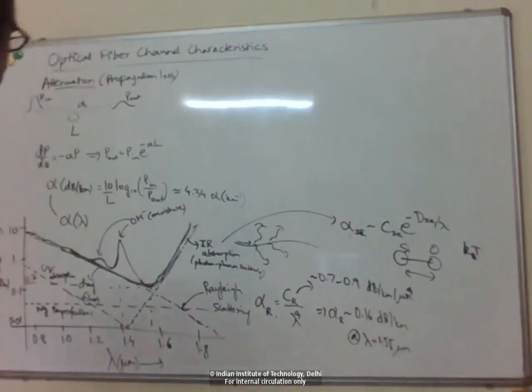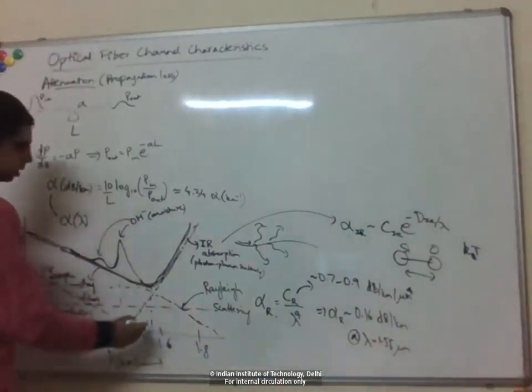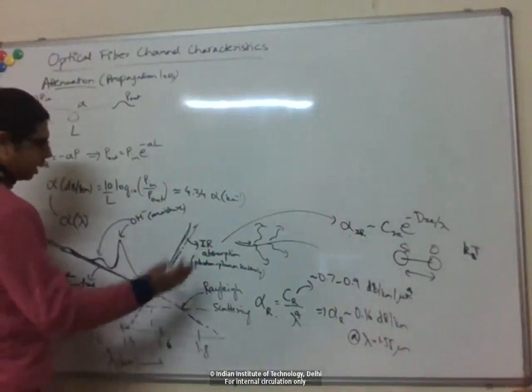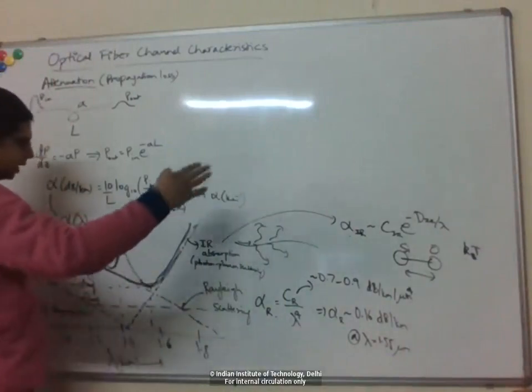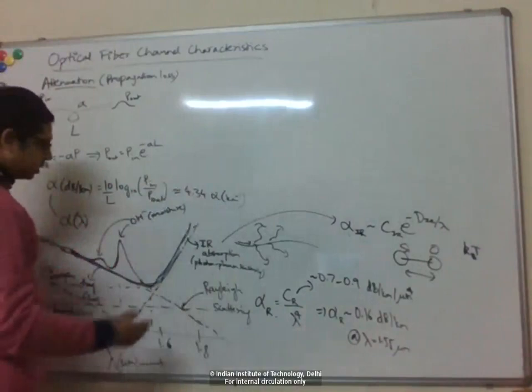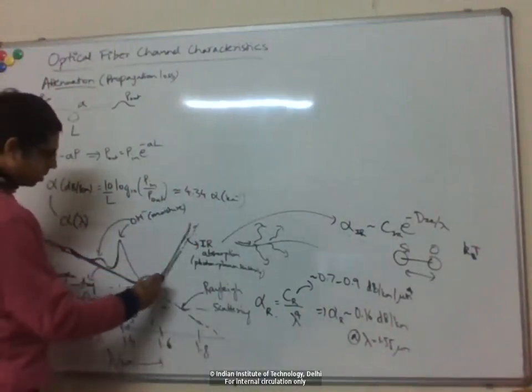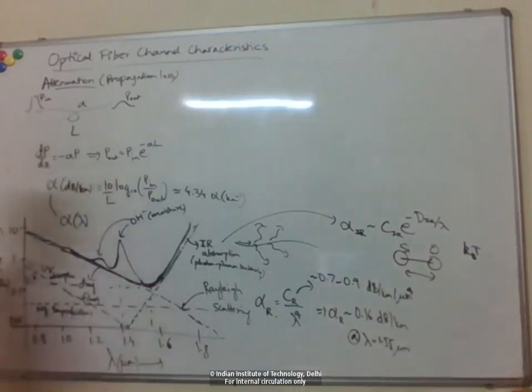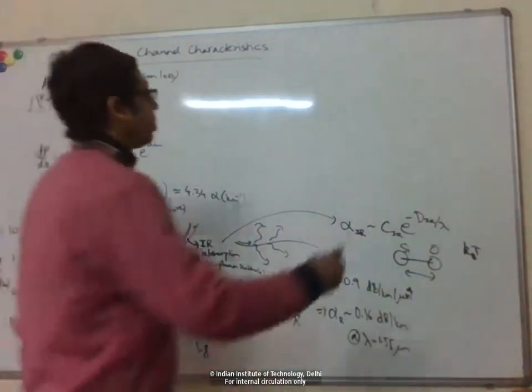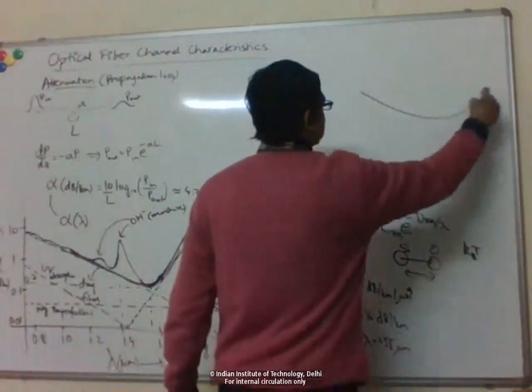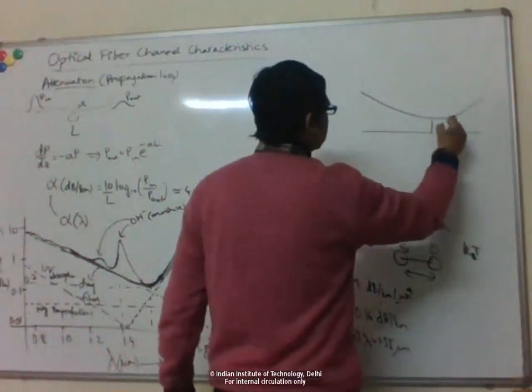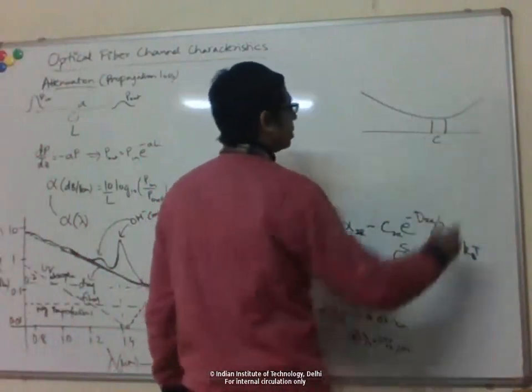U band, yeah. So you can see that. The U band is the last band, which was like 1620 to 1670 nanometer or something. For that, again, you can see that the loss starts increasing. So if you plot the loss across the bands, the minimum loss occurs around the C band.